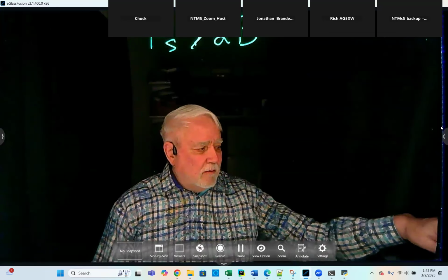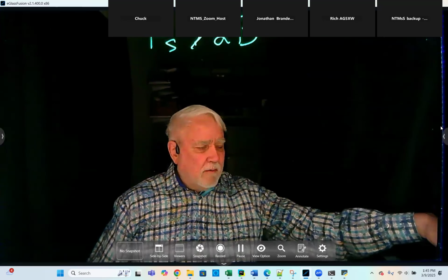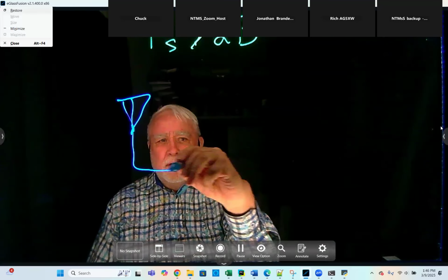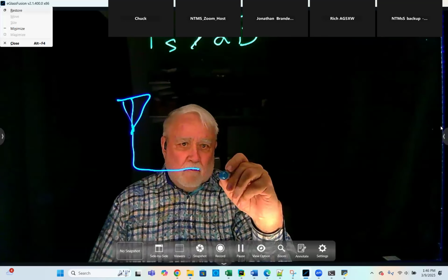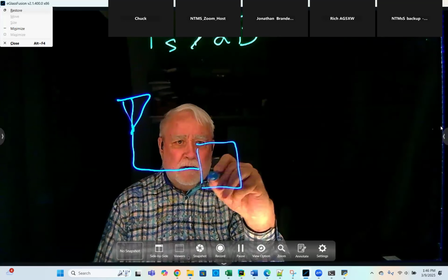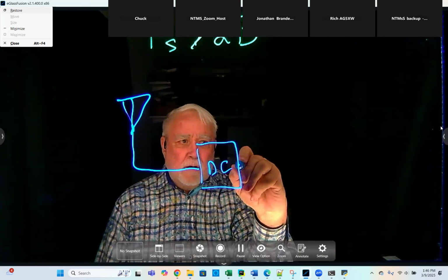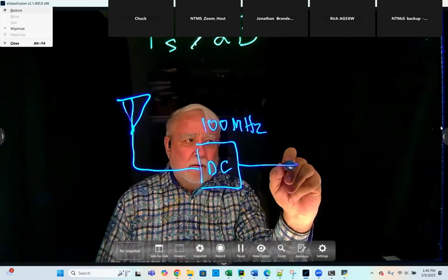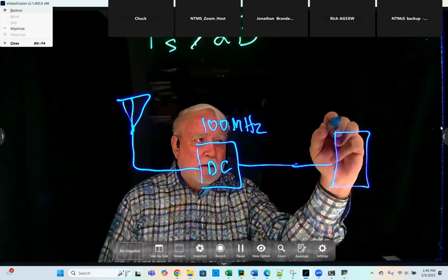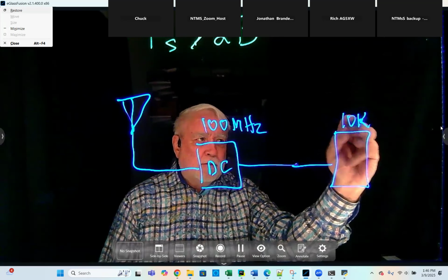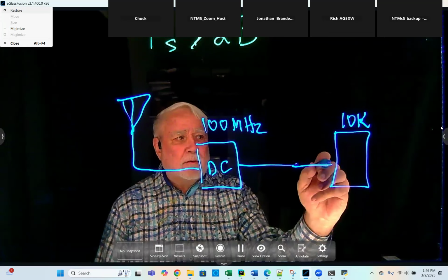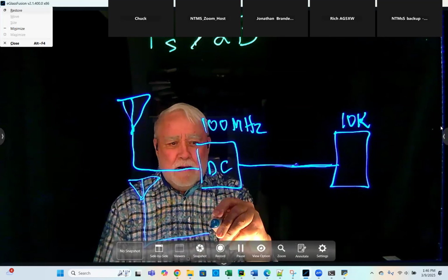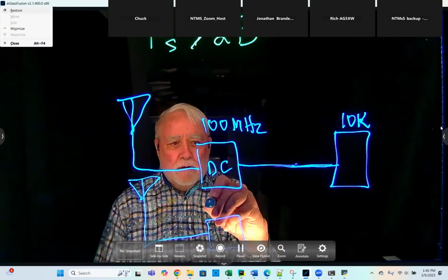Right. So the idea, you guide me along here. I'll try to draw that out, but basically, we have an antenna here, and we've got a stage here that needs to do a little bit of a down convert in order to get it away from like 100 megahertz and take it down to 10 kilohertz, a very samplable frequency, right? But you're dealing with something that comes right in here and it can handle the 100 megahertz straight up.